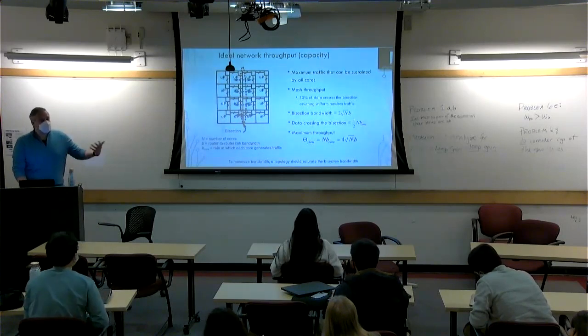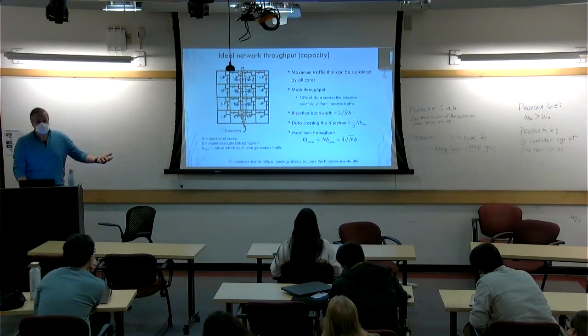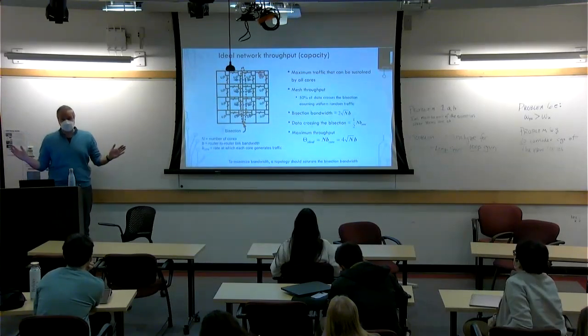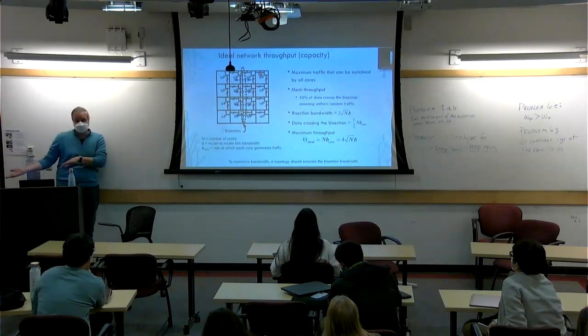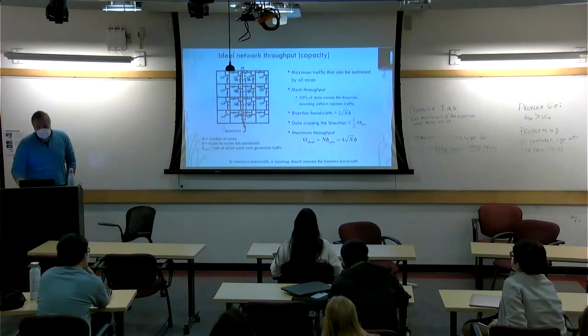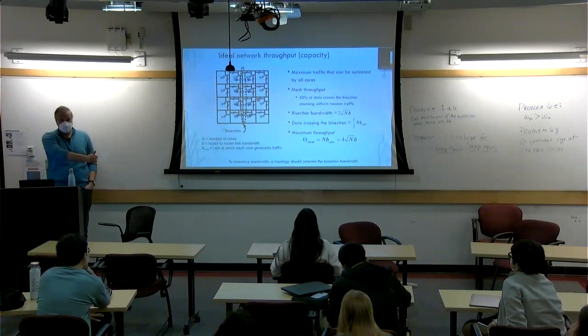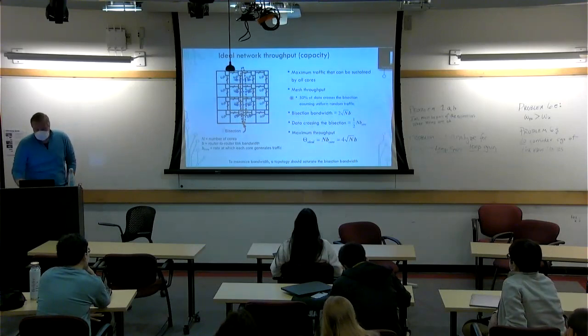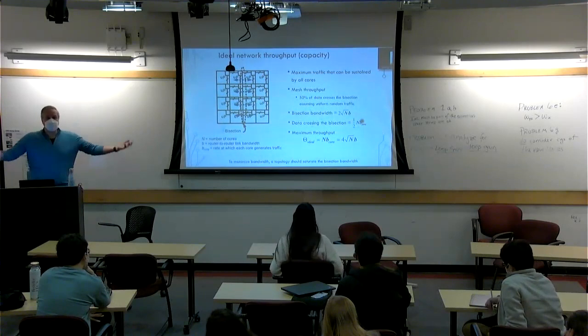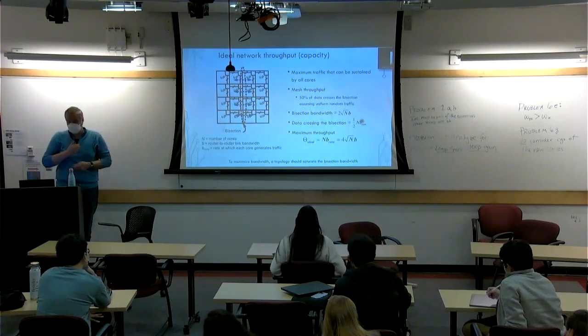If they generate uniform bandwidth, half of what they generate stays here, half goes across. Because it's uniform, 50-50 probability that it's going to be on this side versus that side. Same thing is for these cores. Half of their stuff stays, half of the stuff goes across. Right? So that's why we get this 1/2 of the overall generated bandwidth actually makes it across, right?